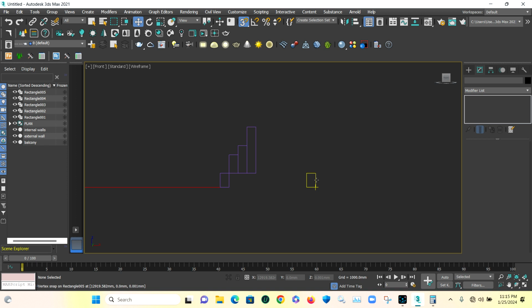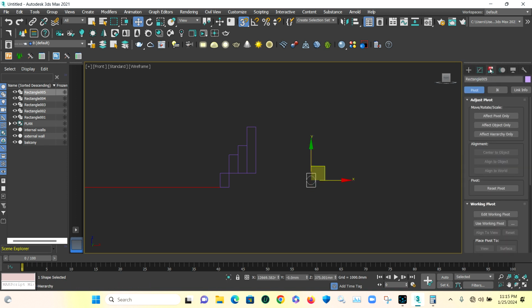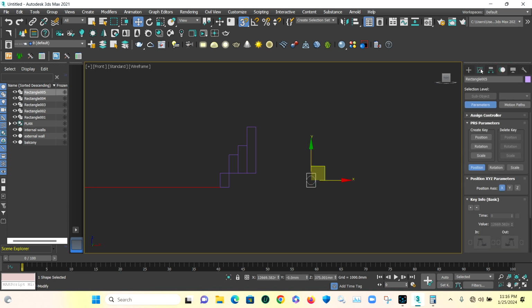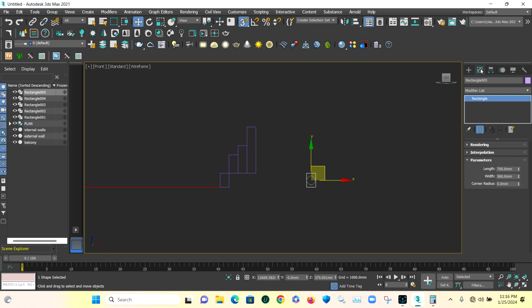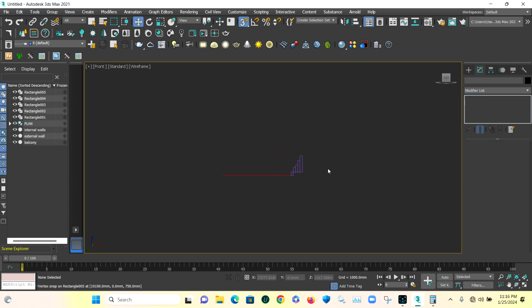Remember, sometimes you might select this and this thing is here, or is here. Make sure you select modify. Be sure it's on modify. That is only where you will be before you see the properties of whatever you selected. Now I will go here and I will make it 3500 as calculated. Then remember that 3005 is from the DPC level.